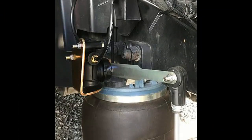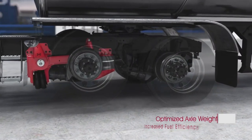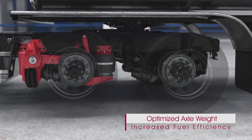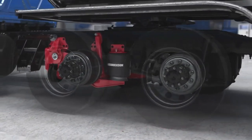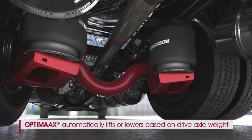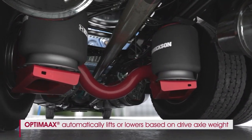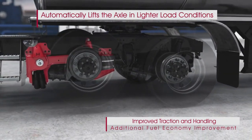Second is air accumulator. Certain advanced compressors require a storage medium to hold the high-pressure air they generate. These storage mediums are referred to as air accumulators. Air accumulators serve the crucial role of ensuring a smooth and gradual transition between different pressure levels within the system. Additionally, a safety relief valve is connected to the accumulator to release any surplus air, maintaining safe operating conditions.